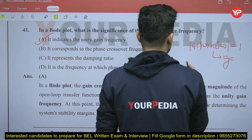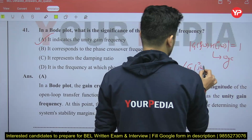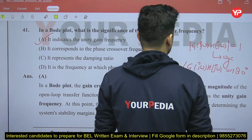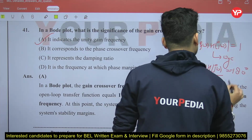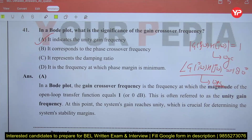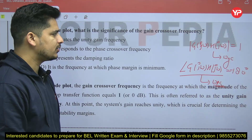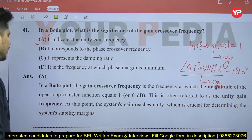If I am talking about the phase crossover frequency, it is the frequency at which the phase of your system is equal to minus 180 degrees. So that frequency is called omega Pc. So there are two frequencies, one is the gain crossover frequency, another is the phase crossover frequency. Gain crossover frequency is the frequency at which your gain is 1, and phase crossover frequency is where the phase of the system is minus 180 degrees.